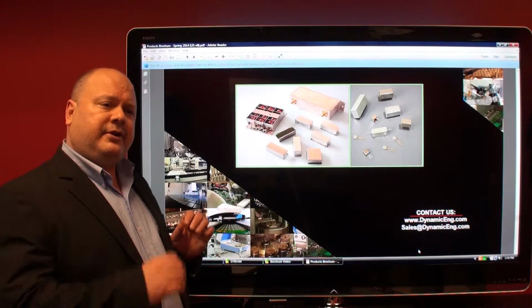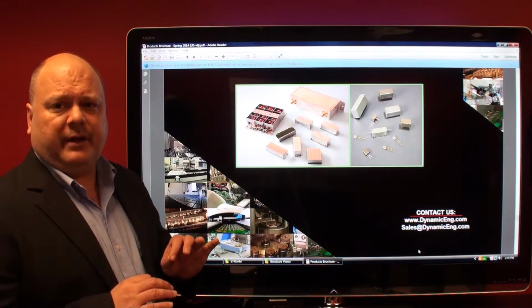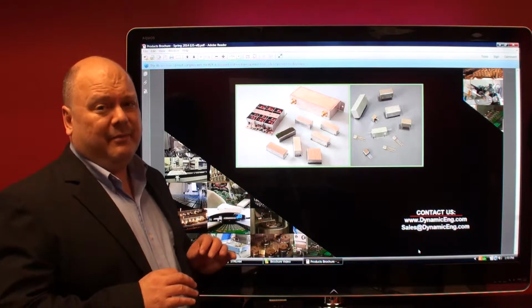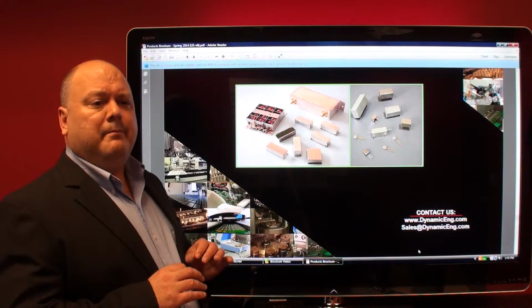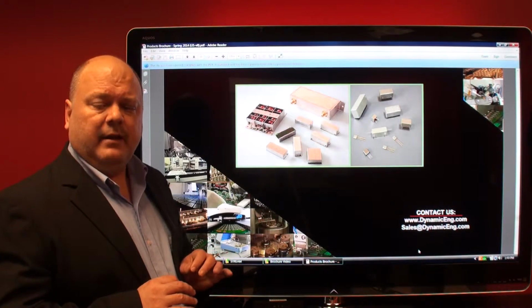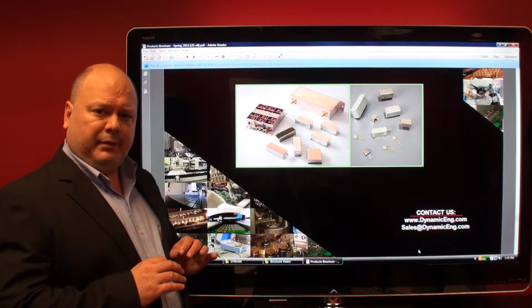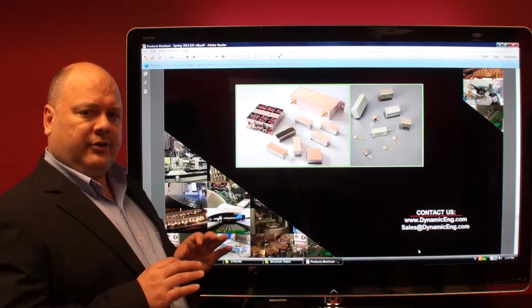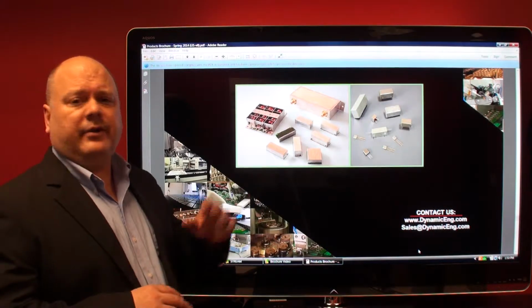If we're going to have crystals that are 100 megahertz and higher, up to 150 megahertz, from a fundamental mode, those are all usually MESA, M-E-S-A, MESA-type crystal technology. MESA-type blanks are specially manufactured. We won't get into the details of those because that's just a whole other subject.